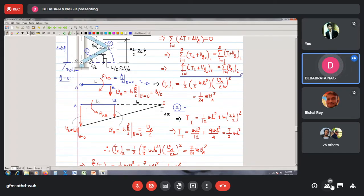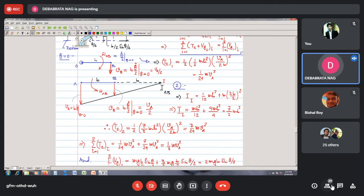Va divided by 2B, because from the geometry we can see that this should be the angular velocity of this member. So I can calculate the kinetic energy of the second member at position 2 like this. So if you now add the total kinetic energy, this becomes equal to 1/3 mVa square.